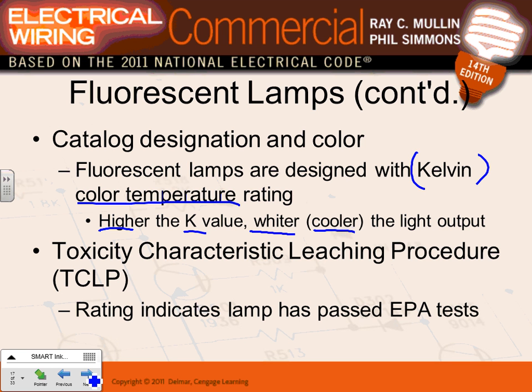This is important because you hear Kelvin all the time: the color temperature of a fixture. Very important, guys. If you have 5,000 Kelvin, you're going to have a very white bulb. If you have 3,000 Kelvin, you're going to have a warm white, they call it warm white, more reddish. Are you guys familiar with that? Everybody's good with that? Higher Kelvin, whiter, almost to the bluish side. Lower Kelvin will get you warmer, more to the reddish.